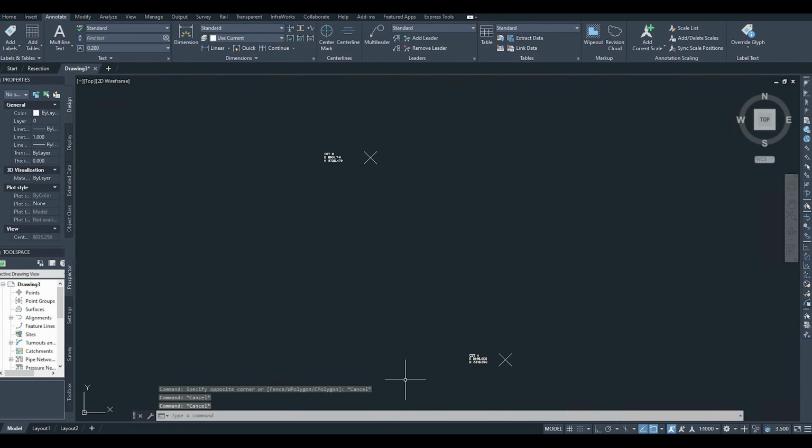Now I have two control stations, A and B. Now the next step, guys, is to draw the circles using the distance between X and A, which is measured using total station, as a radius for the first circle. Now we'll start here. Make sure that the snap down here is activated. This will help you to locate the center of the circle.